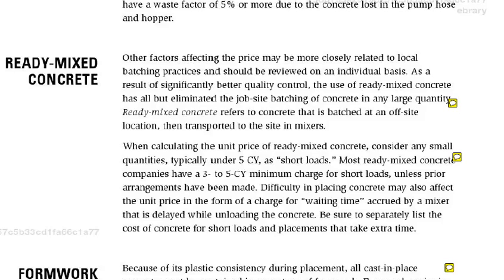So the thing is, though, again, when you order a mix, so often you'll count on a full load. And it depends on the truck. You'll see different types of trucks out there. 10 yards, 15 yards. More than that, and the truck is overloaded, and you can't really use it on public streets. You could use a larger haul when you're working interior to a site. But for regular transit mix, you're talking about 10 or 15 yards.